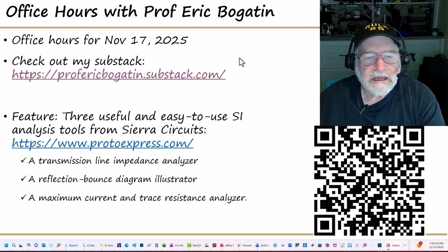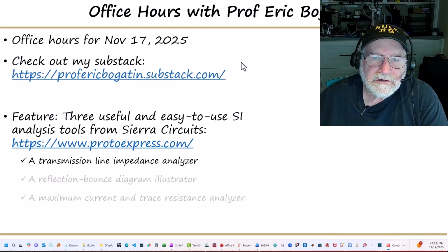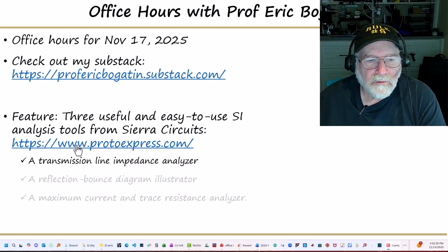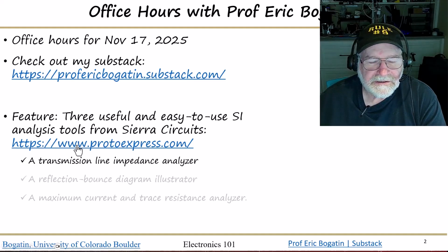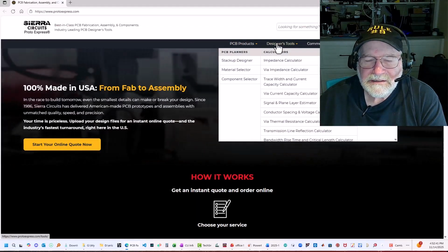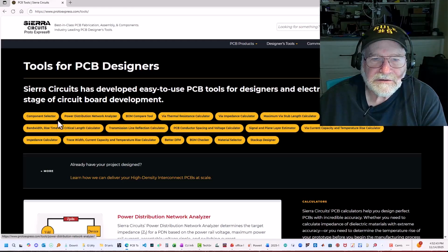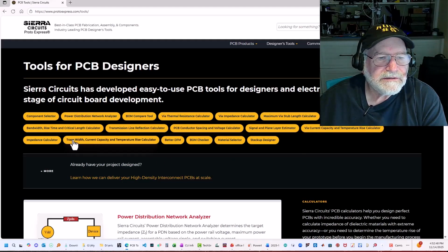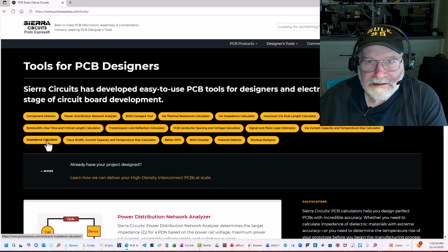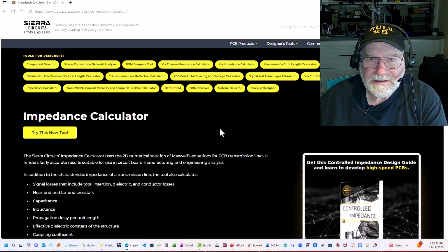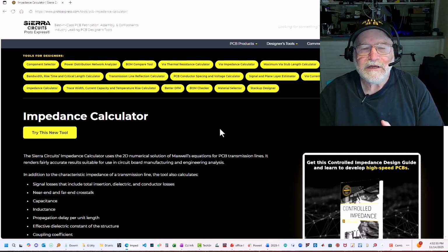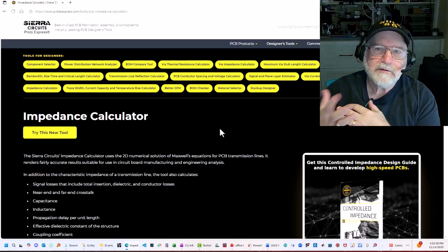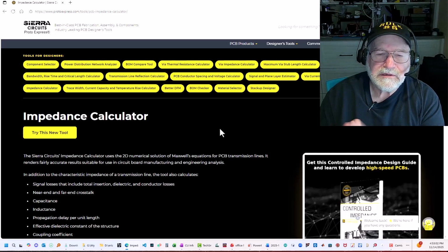So let's get started, and in this particular video I'd like to review the transmission line impedance analyzer. To get there, all we have to do is go to the Sierra Circuits website, and right at the top here we see designer tools. We click on that, that takes us to all the designer tools. The first one that we're going to look at is this one that says impedance calculator. Its sole purpose is to take stack up information and turn it into some of the electrical behaviors, characteristic impedance, capacitance per length, inductance per length, time delay, that sort of thing.